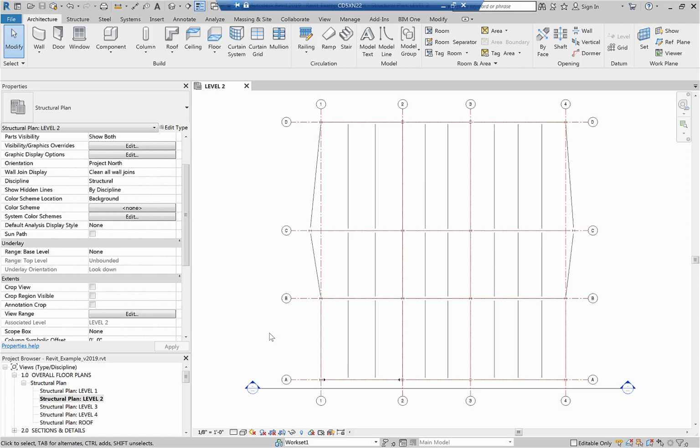In this tutorial, I'm going to show you how to lay out your loads inside of Revit. At this time, you should not be making any geometry changes to the model, and you have verified that no discontinuities exist within the model. Let me also remind you that you should be using the Revit template that is set up to export your model. In order to view the loads, ensure Structural Loads is checked under the Analytical Model Categories tab within the Visibility Graphics.